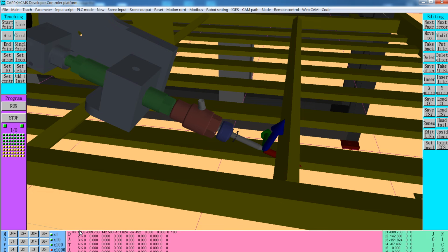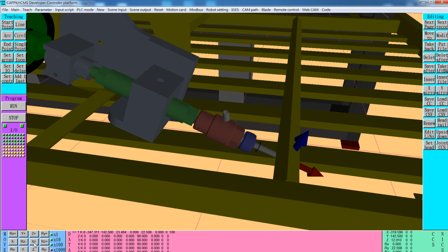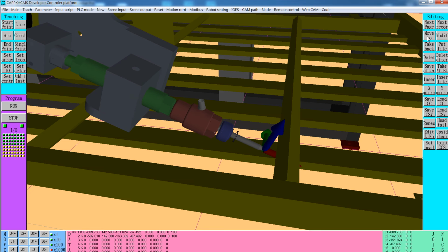this coordinate as first line, first instruction, and then change back to Cartesian coordinates and use S plus to thrust the tool in to Z equal to 12 at the welding position, and change the coordinate system to joint mode, and lock the second point. The third point will retract to the first point position, so we use head to move to the first point,